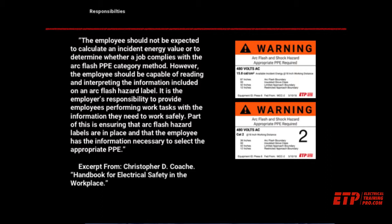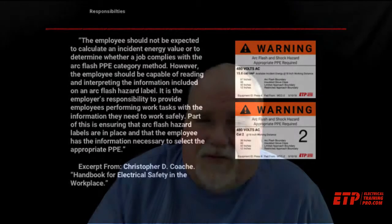So 7E says that equipment has to have an arc flash label. A lot of people take that to mean, and it has for years, that you do an arc flash assessment, you do an incident energy analysis, then you get your labels. Well, you need to have labels even if you've not had that done, even if you don't intend to ever have that done. You still need labels.